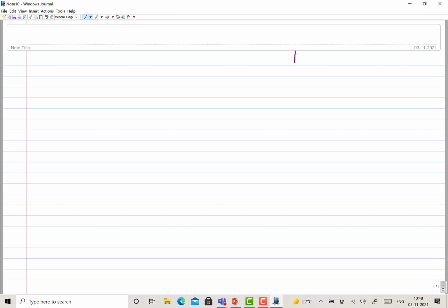Usually we limit the sulfur and phosphorus in steels below 0.05%. If the steel is having more than 0.05, then it will become crack sensitive, and we would like to avoid that situation. Okay, so we want that the sulfur and phosphorus content in steel is maintained below 0.05, otherwise it will become very crack sensitive.